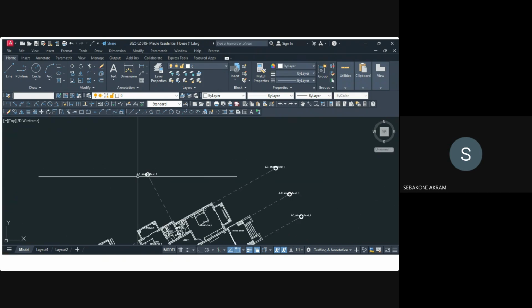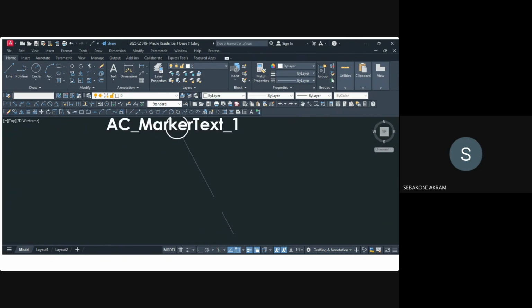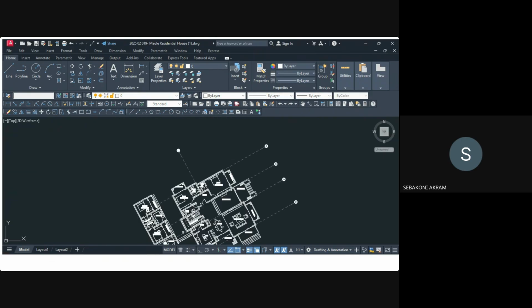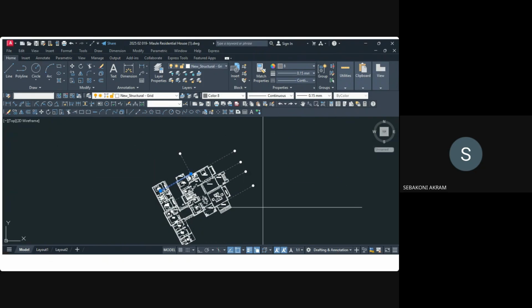When you just explode them, for some drawings, let me say if an architect uses Revit, when you explode they stay. But if an architect uses AutoCAD, in most cases they also come to this. So what we do, instead of exploding, we highlight them. There is another function called burst. You burst them instead of exploding them.